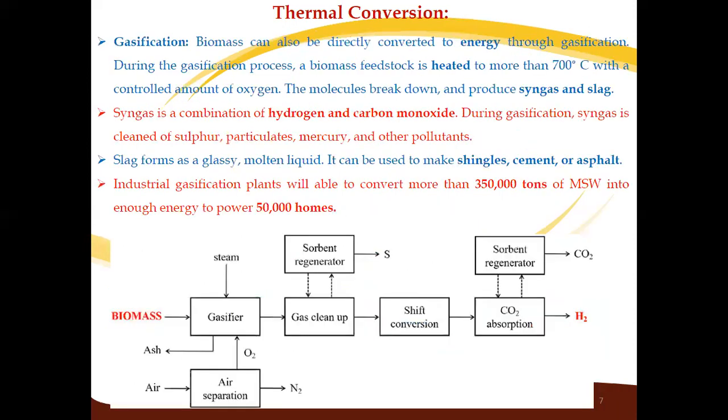The next process of thermal conversion is called gasification. In gasification, biomass can be directly converted into energy. During the gasification process, the biomass feedstock is heated to more than 700 degrees Celsius with a controlled amount of oxygen. The molecules of the biomass break down, and it produces synthetic gas and slag.